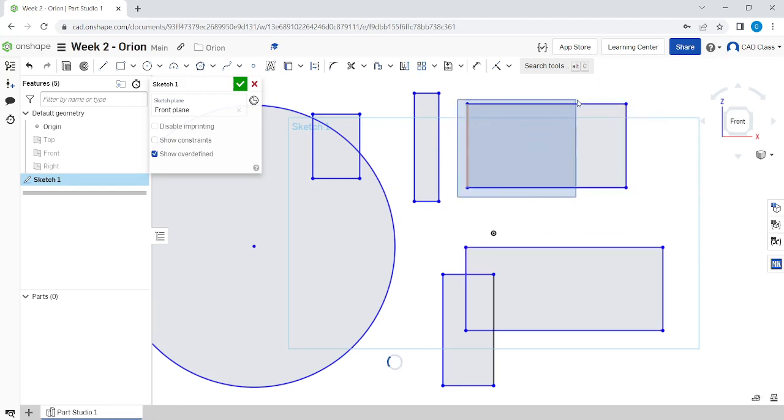Now, one thing that I want to highlight, and this is pretty common across CAD programs: it doesn't matter bottom to top, but if I select first on the left and then move to the right, you can see the box is blue. But if I move to the left instead, you can see the box is yellow. That is important.